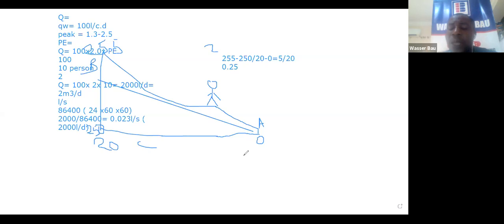Yeah, that's a good question. Some pipes have a maximum overburden that they can take, and these are usually specified for the pipe. If you are using a bigger diameter pipe, the distance we are giving is not the invert from the bottom, but we are looking at the overburden.